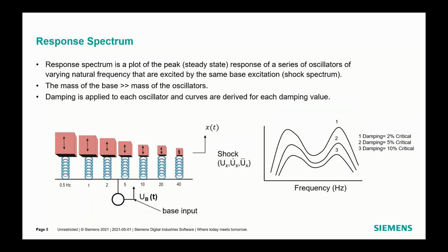What they basically do in the simplest terms is they recover the response of single degree of freedom systems to discrete inputs, and then they just sum them together to form a combined response. And in the traditional sense, they've always used damping at the time that they developed the response, so that you basically would interpolate between curves in order to find the damping coefficient that you wanted to use for your analysis. So the analysis itself becomes a simple linear analysis.